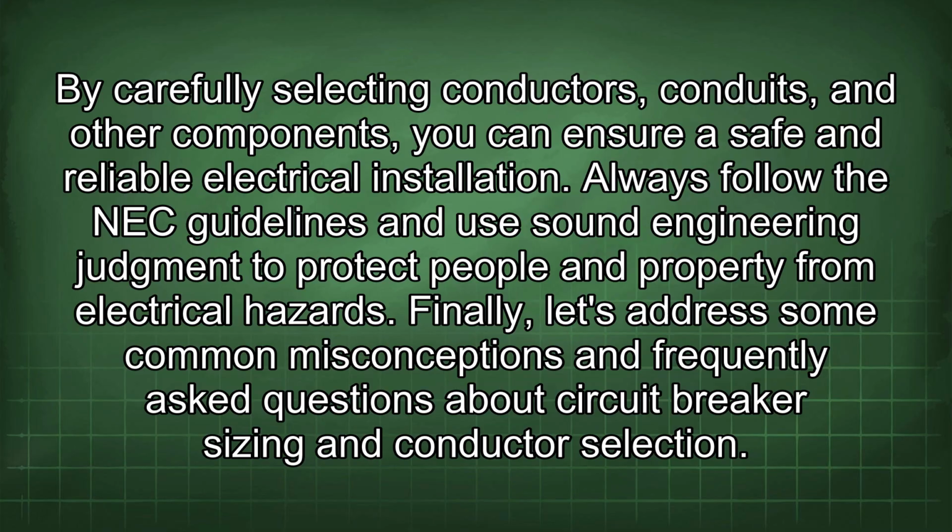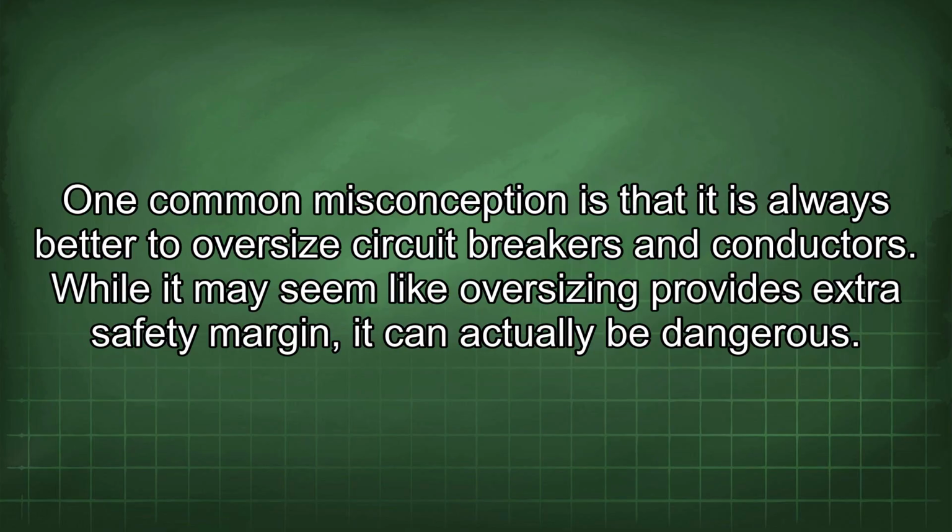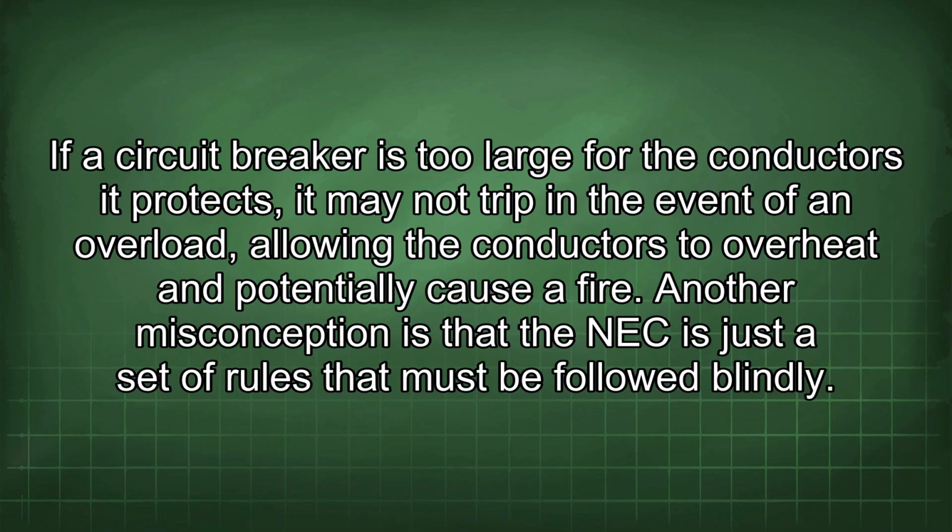Finally, let's address some common misconceptions and frequently asked questions about circuit breaker sizing and conductor selection. One common misconception is that it is always better to oversize circuit breakers and conductors. While it may seem like oversizing provides extra safety margin, it can actually be dangerous. If a circuit breaker is too large for the conductors it protects, it may not trip in the event of an overload, allowing the conductors to overheat and potentially cause a fire.